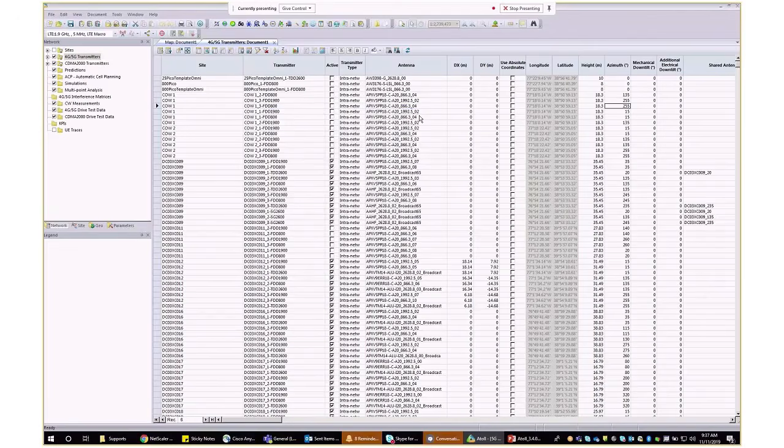So now we'll talk about the Atoll working environment. The Atoll working environment is divided into three parts basically: explorers, maps, and data tables. As I told you, the Atoll working environment is very flexible and supports standard Windows capabilities such as simultaneous opening of several windows, moving windows or objects by dragging and dropping them. Data and objects contained in Atoll documents are accessible in different ways.